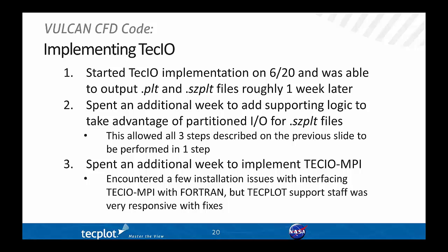And then finally, there was about another week to implement the TecIO-MPI libraries. TecIO-MPI for structured grids is a fairly new technology for Tecplot, and I believe I was one of the first beta testers of that. There were a few issues with getting the CFD code, which is written in Fortran, playing nicely with the TecIO-MPI libraries, which are written primarily in C++.